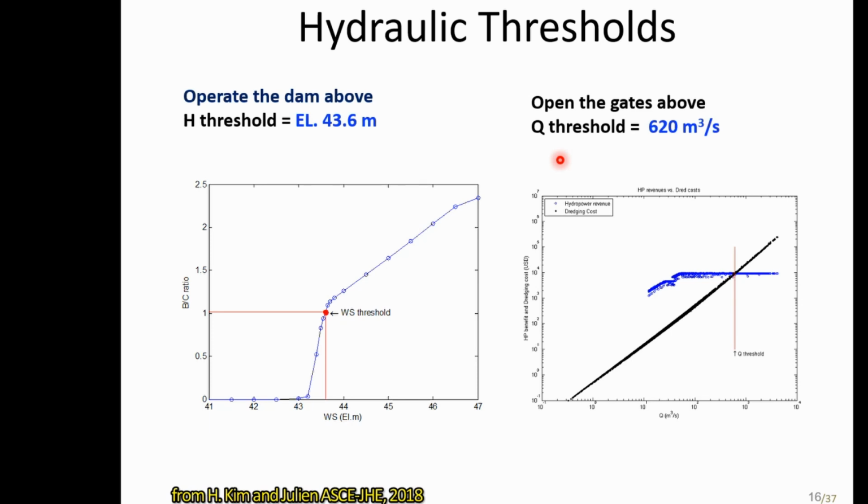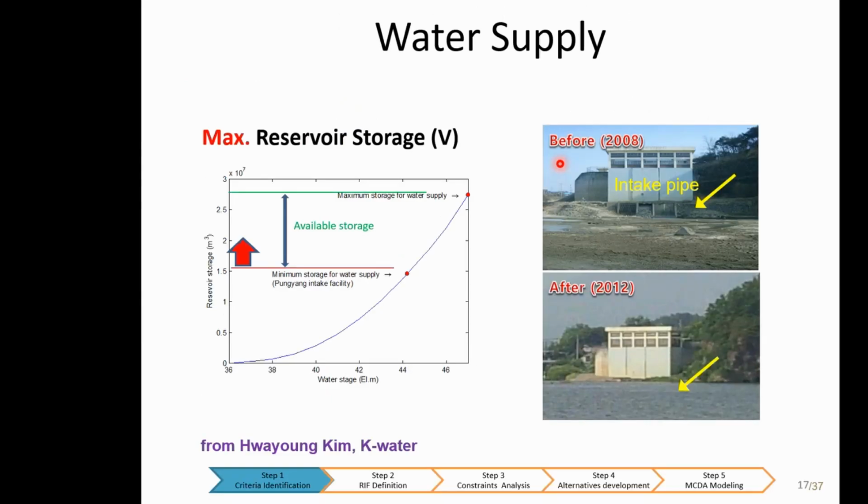Dr. Ettema yesterday talked about something very similar with the ice problem at the intake of one of his projects, I forget which one, I think on the South Platte River, where he said if you get this condition, that condition, low flow and temperature and whatnot, you should just shut down the plant and not have diversions into your irrigation canal or your water reservoir and so forth. So it's not really a new concept, but it's something that is helpful.